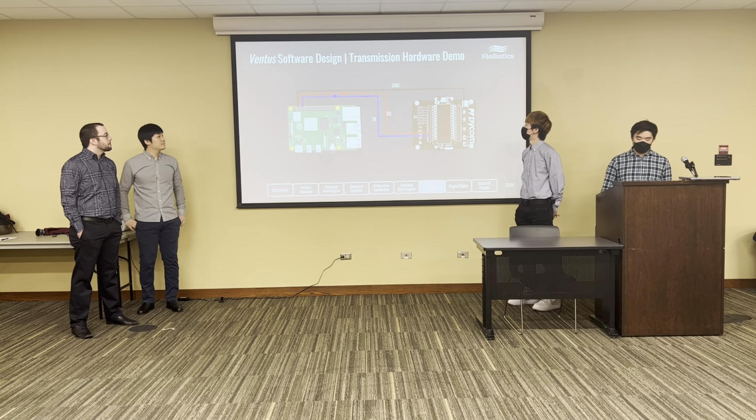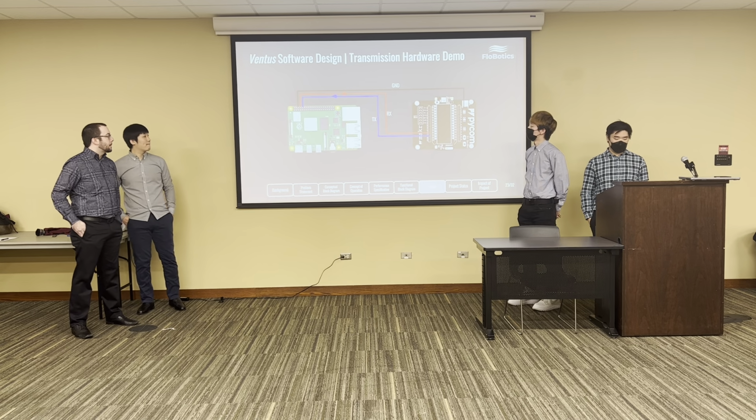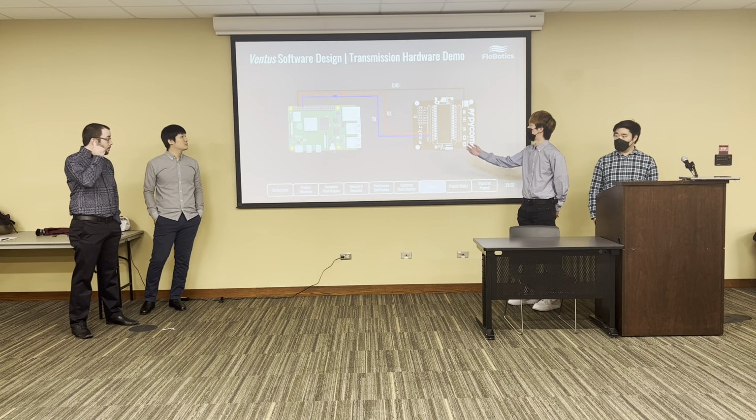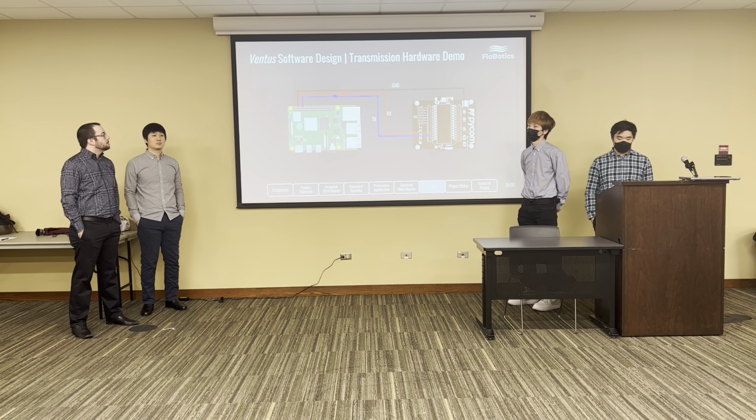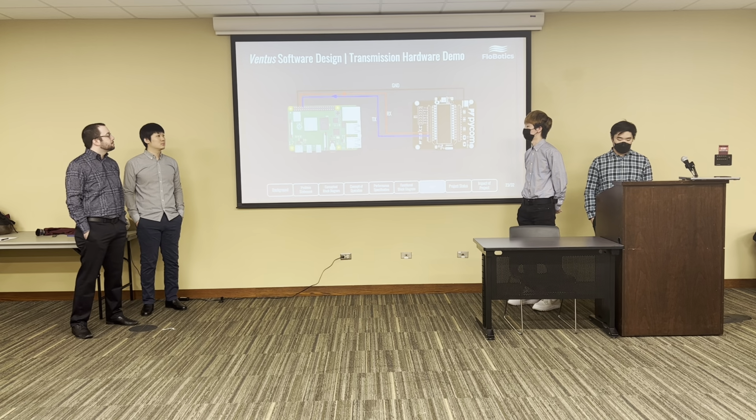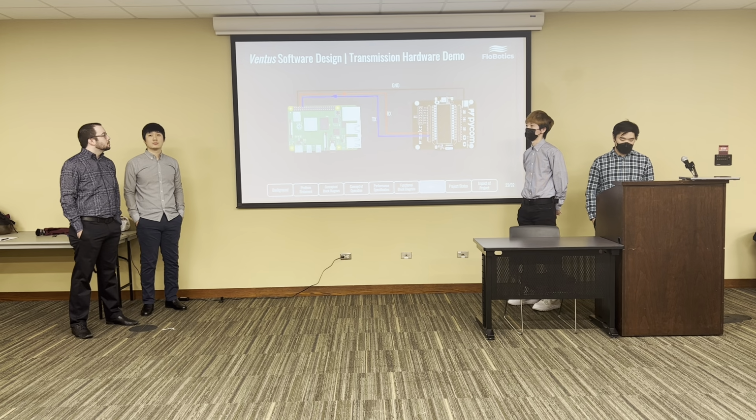So here is our basic connection between our front end, which is the Pi, and the wireless transmission. We're using the UART, for which we need ground and a receive and transmission pin.